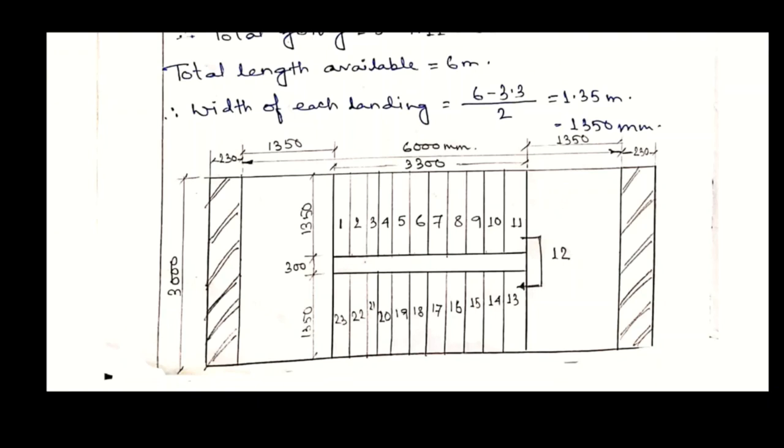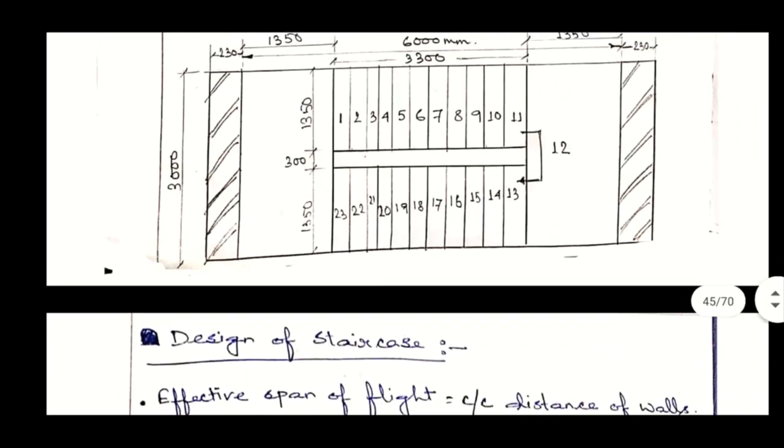So, before starting that, we have to know what a waist slab is. Look, a waist slab is nothing but a normal slab which is at some inclination angle between two supports, mainly used in RCC staircases. The waist slab rests on beam to beam, and the main stair reinforcement goes up to the mid depth of the resting beam. Waist slab thickness will depend on the length of the stair run. Okay. So let's start the design.